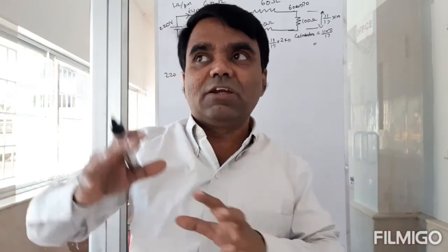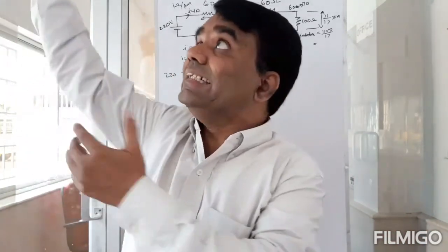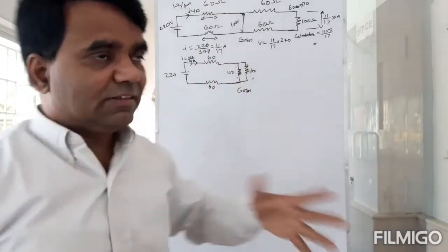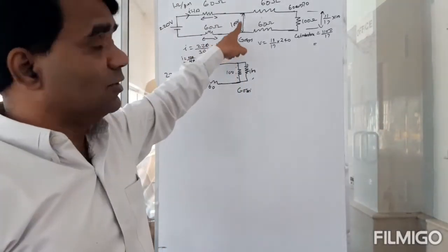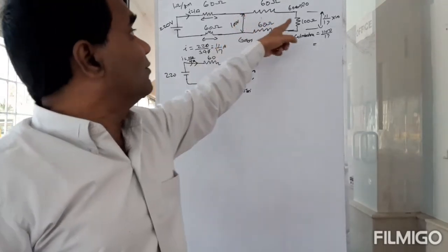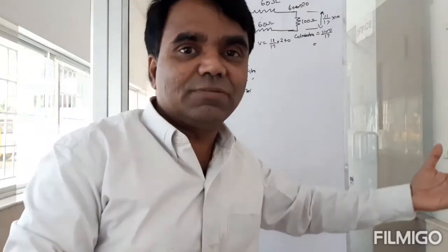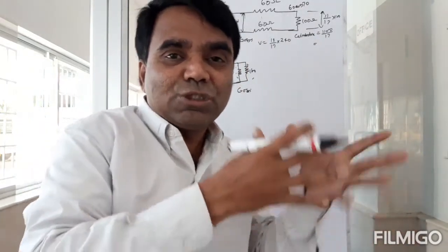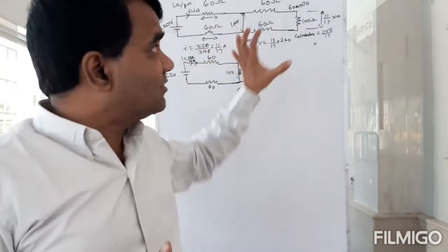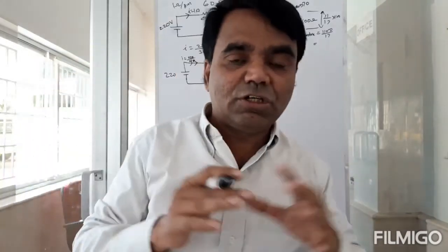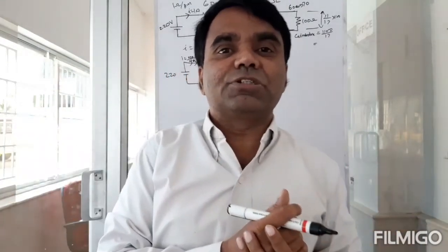So you will be wasting a lot of energy in transmission itself, and by the time that guy gets it, it will be much less. As you saw, 220 volts, you get only 100 volts here. Okay, and then here you get about 60 to 70 volts, and if it is much farther, much less. So the instrument also will not work well. So these are the disadvantages of long distance power transmission.